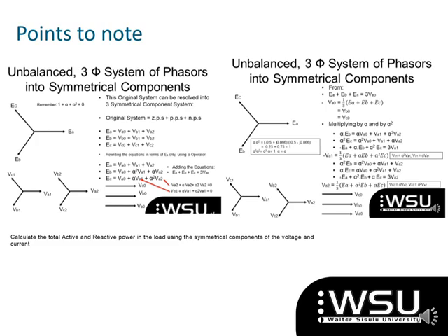So what you had in the actual test is that you had to calculate your currents and you were given VA, VB, and VC. Because it was on A phase, you were going to take those currents that were given, IA0, IA1, IA2, and then you had to work out your VA0, VA1, VA2, and you work those out utilizing your EA, EB, EC that you were given.